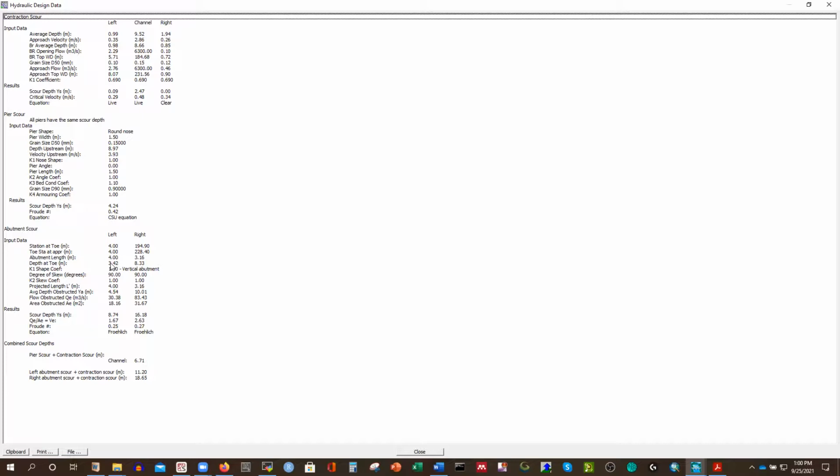You have to select the worst situation where we have the highest scour and we have the highest velocity, flow rate, everything. Then if you construct the bridge based on this worst condition or situation that may occur in future, your bridge may survive a 100-year flood, right? Otherwise it will be washed out. So if you have any design fault, and if you're not experienced, if you didn't face that problem previously, that's why you need experience on that.